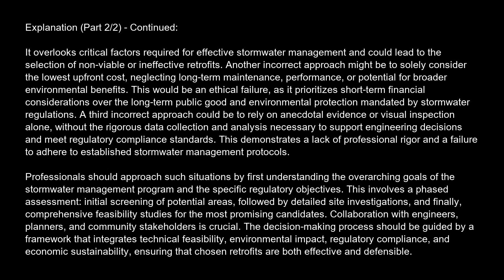Professionals should approach such situations by first understanding the overarching goals of the stormwater management program and the specific regulatory objectives. This involves a phased assessment: initial screening of potential areas, followed by detailed site investigations, and finally, comprehensive feasibility studies for the most promising candidates. Collaboration with engineers, planners, and community stakeholders is crucial. The decision-making process should be guided by a framework that integrates technical feasibility, environmental impact, regulatory compliance, and economic sustainability, ensuring that chosen retrofits are both effective and defensible.